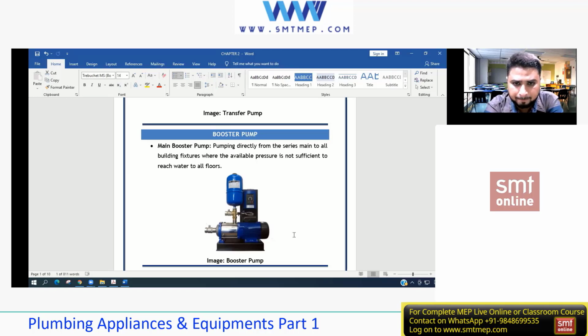Following, everyone? Sir, can you please tell again what is the difference between the main booster pump and the hydro booster? I have not done the hydro yet. Let me come back again. Everyone, I'll try to be thorough. First of all, let's see what exactly a booster pump is. A booster pump is a pump used to maintain the pressure in the line. Just to maintain the pressure, which makes sense in terms of what pressure, what kind of pressure, or how much pressure.